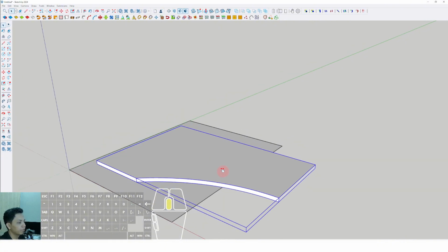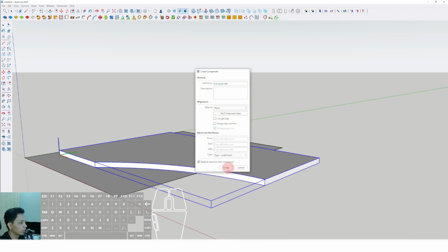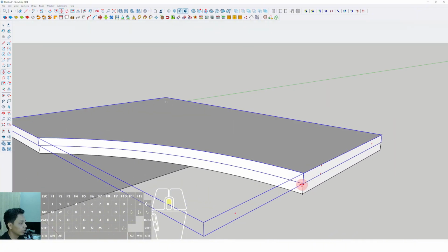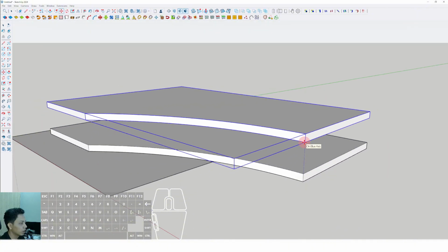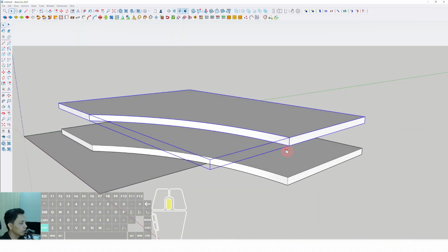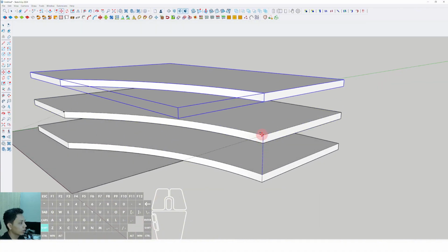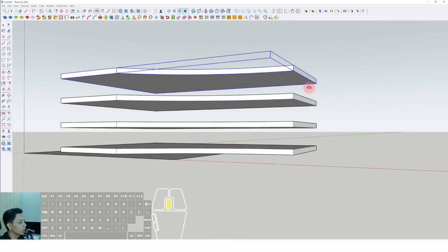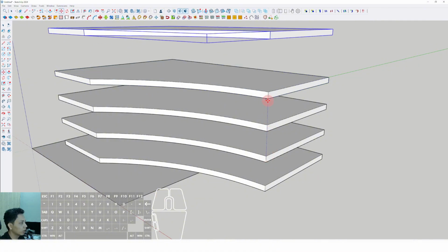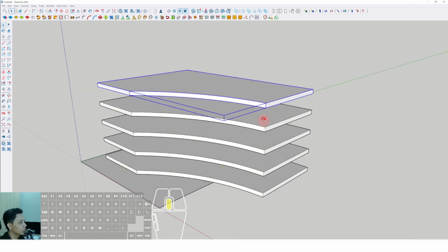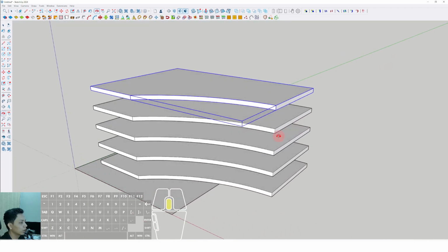Triple click and make group, and then we can make component, just create. Then you can select move, press Ctrl, and then place to this position. Then we can move it up around 3.6 meter from floor to floor, floor to ceiling. Then we can select move, press Ctrl, then place to this position. Okay, well, and then we can make maybe more stories. Okay, this one.